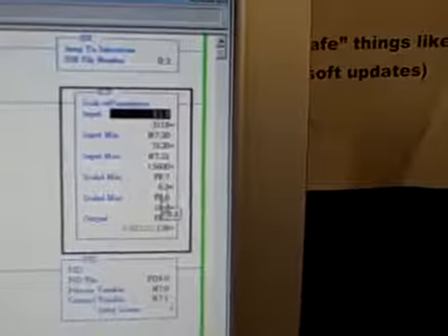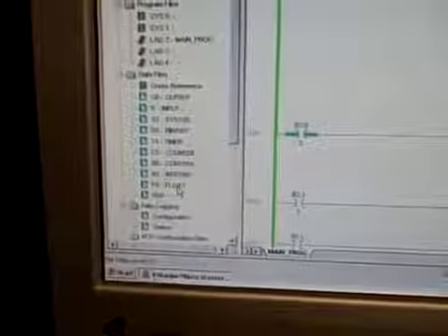And notice, in both these cases, we have those low and high range parameters stored in floating point number registers, so F87 and F86. We come over here to the floating point files, and here we have F86 and F87. So F86 is where it stores the upper range value, F87 is where it stores the lower range value.